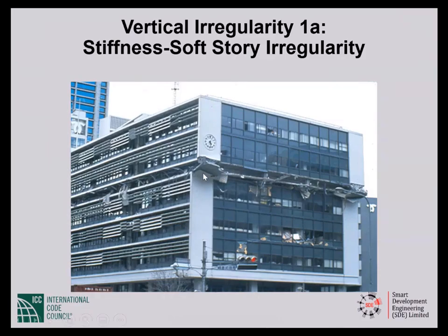And this is a very, very good example of that. I think I showed you that the day I was talking about earthquake experience. This is the City Hall of Kobe. The bottom part of the structure has steel reinforced concrete. The concrete has steel shapes concealed within it. But at that level, the steel shapes were discontinued, giving us a stiffness discontinuity, and that is the level that failed.